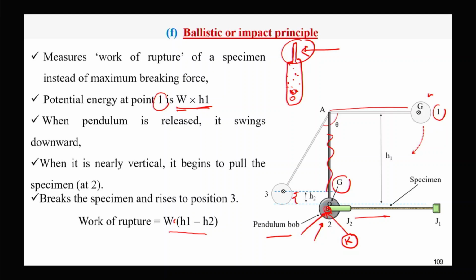To eliminate this problem, we use the point of percussion, where the reaction force is minimum. So all the energy is used to rupture the specimen.